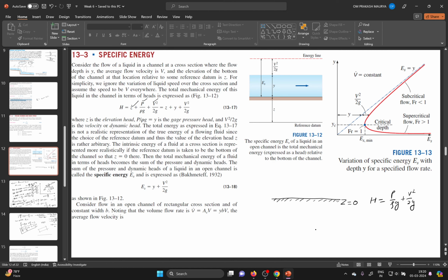So your pressure here is rho g h. We have considered the uniform flow. In case of uniform flow, your pressure varies like that, and you can also write rho g y. So that is the hydrostatic pressure distribution. Here, always remember, we have used the hydrostatic term, but the water is flowing, so do not get confused. We use hydrostatic because if the water is in static condition, then the pressure distribution is rho g h. In case of uniform, steady flow, the pressure distribution is similar to the static one. So that's why for flowing water with uniform and steady flow, we assume the pressure follows the hydrostatic distribution.